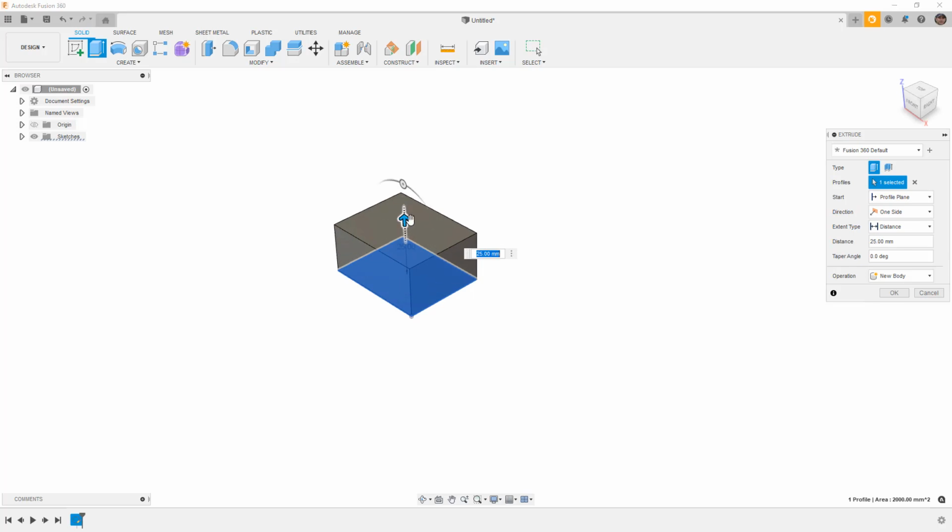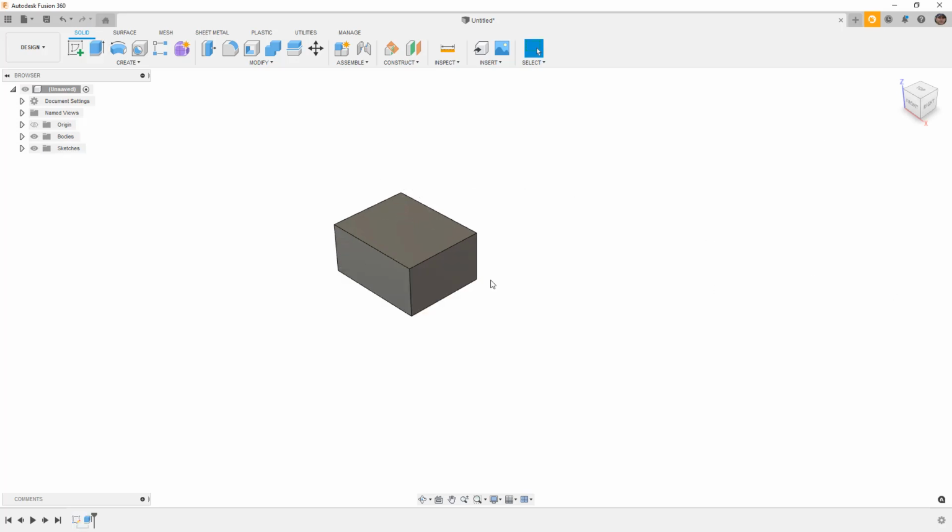So here we're going to extrude this into 3D, and now we've created a 3D B-rep. This B-rep, or boundary representation, is the mathematical equivalent of the solid volume or body that we have. Basically, using math and representing the vertices and edges and faces based on the math behind it gives us nice, clean geometry. This is critical when we're talking about manufacturing. If we were going to machine this block or if we were going to mold it, we need that critical information to get these clean surface and solid bodies.